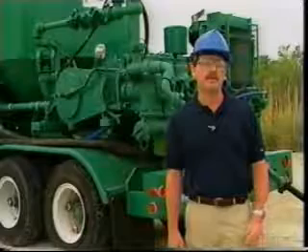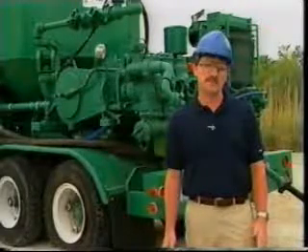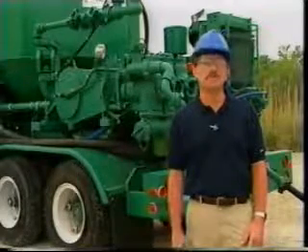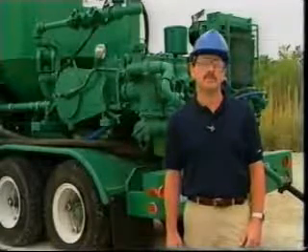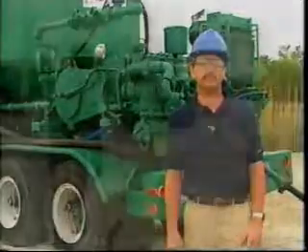On the other hand, if the acid injection rate is too low, that is, less than 1/4 barrel per minute during the hydrofluoric acid stage, it may be necessary to reduce the acid volume and retreat the well at a later date. Okay, let's look at the equipment and some quality control measures.